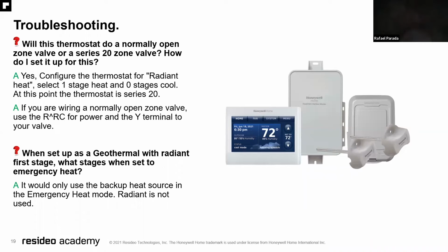But for the ones that they are, what we need to do is to configure the thermostat for radiant heat. We are going to select on the heating stages to have only one stage and no stages for cooling. And this is how we configure the thermostat for Series 20. So we can wire up with the R and the W and the Y wires. And remember, we need to keep the jumper between R and RC. And if we are working with a normally open zone valve, we're going to configure the same, but we're going to connect only the R and the Y wires. We have only two wires. And remember, the jumper between R and RC is a must.